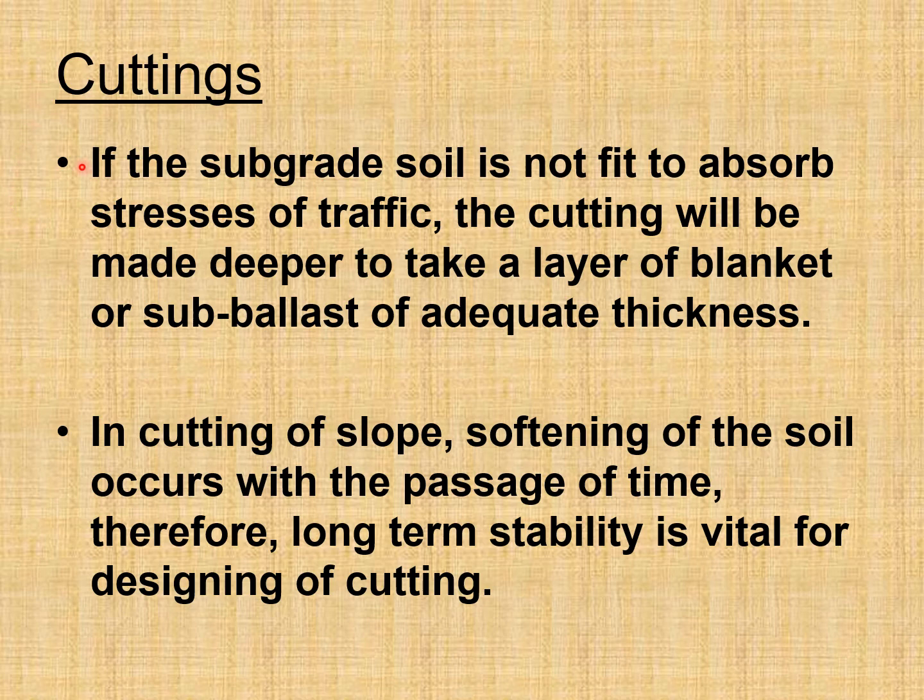Cuttings. If the subgrade soil is not fit to absorb stresses of traffic, the cutting will be made deeper to take a layer of blanket or sub-ballast of adequate thickness. In cutting of slope, softening of the soil occurs with the passage of time. Therefore, long-term stability is vital for designing of cutting.